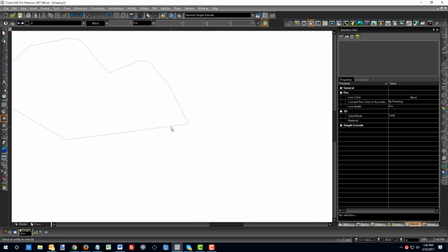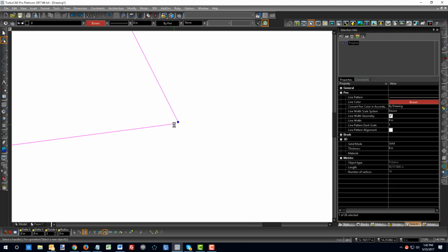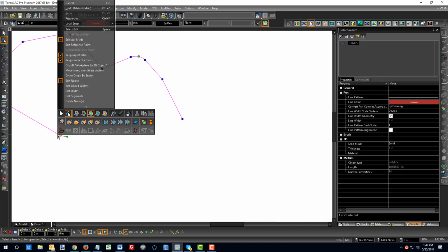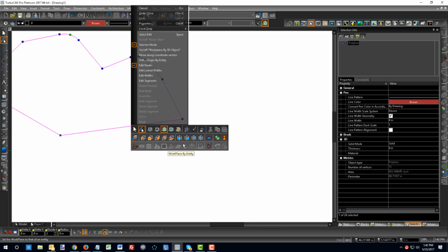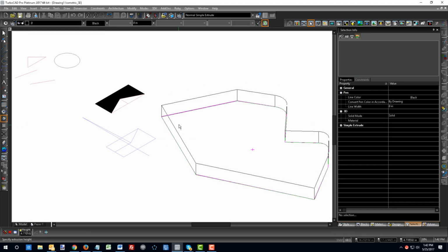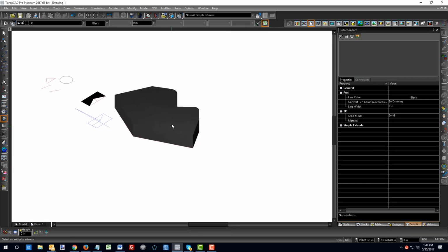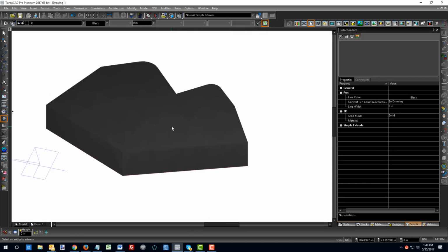So again, we'll use the edit tool. I'll delete this node because I don't actually want to create a second node like that when I close it. So we'll get rid of these two with the control button. Okay, and then I'll come here, right click, and go down to the bottom here and say close. And now when I do the same thing in isometric mode, extruding this, aha, I get a nice correctly made 3D element.